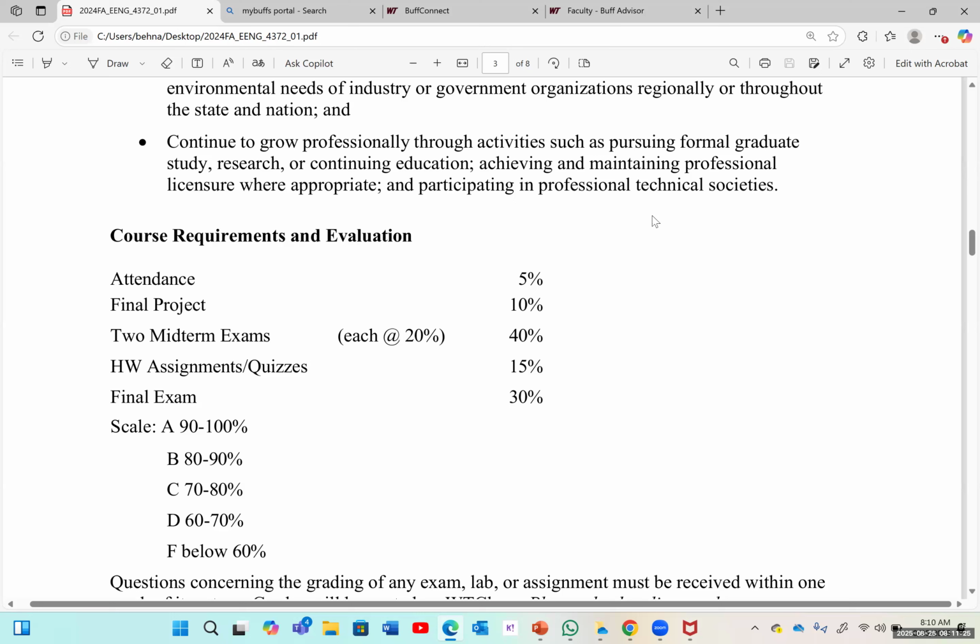The PCB board, you design it and you send it. There are a lot of companies like JLCPCB that will print it, and usually the first 5 PCBs you print are free. You just have to pay the shipping cost. But you have to start your final project at the middle of the semester at least, because printing those PCB boards usually takes a couple of weeks. Sometimes you don't find the parts that you want, and having those shipped now takes a few weeks.